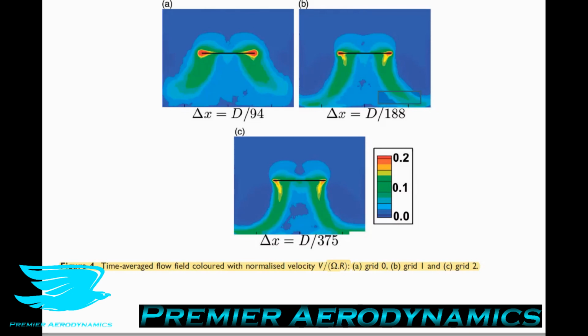So this qualitative comparison shows that obtaining grid independence results remains a difficult task with pure Cartesian grids. In other words, in this particular case with a rotor with 2 blades rotating around, the LBM method, the Lattice Boltzmann method, did not perform adequately compared to the first simulation that we saw. The reason why is because of the Cartesian grid, as I mentioned.